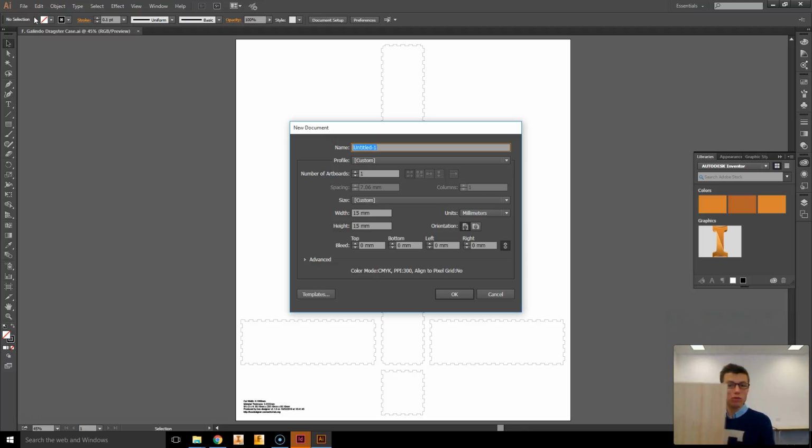Now, this 3mm piece of plywood is cut down so it will fit in our machine, and I have specified its size with a tag on sticky tape in that corner. We'll remove this once it's in the machine, so if you're the first person to use it, you're going to have to make sure you create a file that's this size. It goes in so that the long edge is its width, and its height is the short edge.